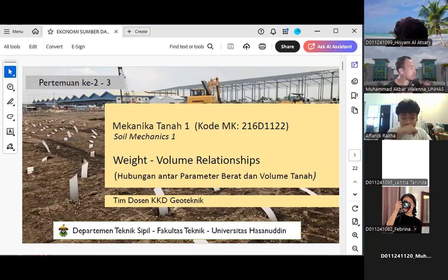When we know the grain size distribution, we can also predict how quickly the water dissipates from the soil, or how quickly or slowly the water is going to be held or mobilized throughout the voids of the soil. Ultimately, what this information tells you is about the stability and the strength of the soil.